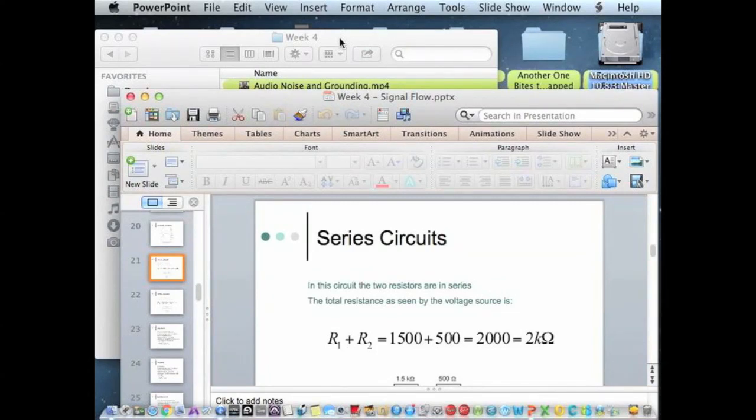It's a passive device with a capacitor and resistor. You change the resistance value by turning the knob, and as you change it, more high frequencies go away. When you think that you're adding more bass, you're actually just taking away top. And when you open it all the way, then you get the most high frequencies. And that is in every passive Strat. Any passive guitar has that as a tone control.